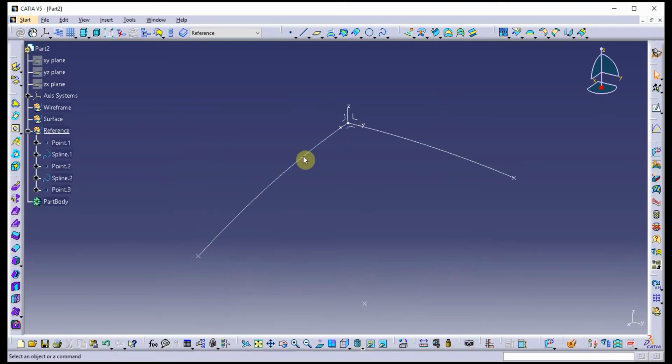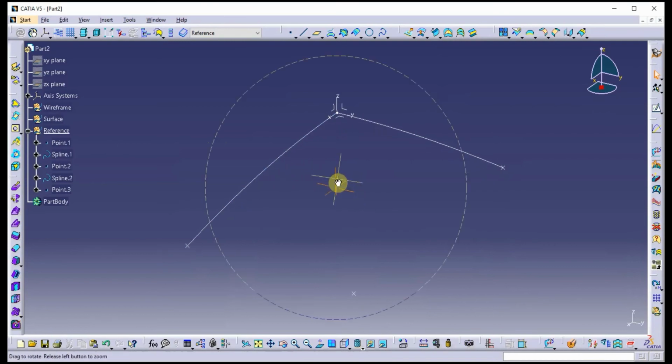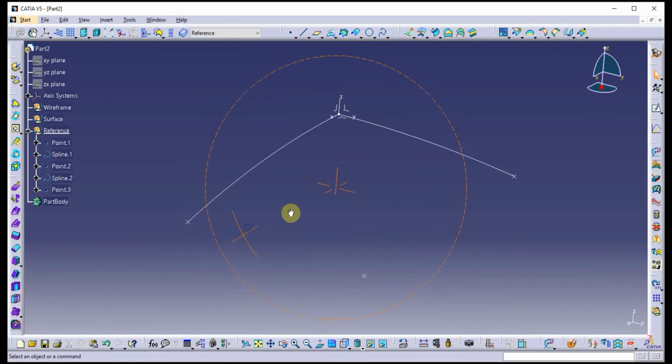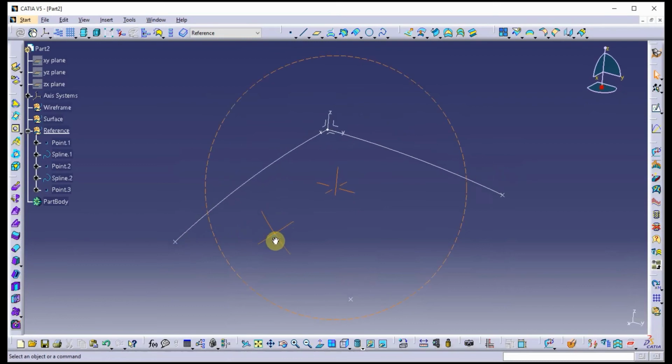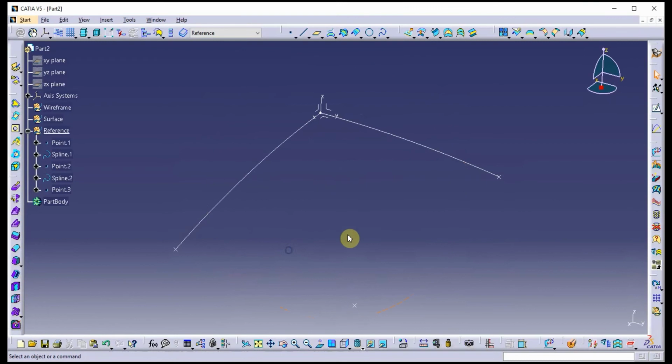other half over. So I call this a seam, and I am very picky with my students about making sure they have good continuity over a seam. So again, this is primarily for my students to make sure they understand my expectations for seams. I'm going to use the multi-section surface tool for this in CATIA's GSD workbench, and my goal is to have G2 continuity over this seam. So let's begin. Let's look at what I have here.